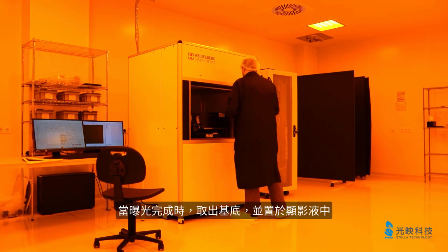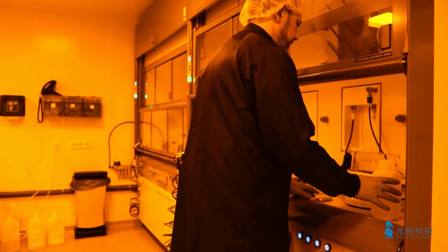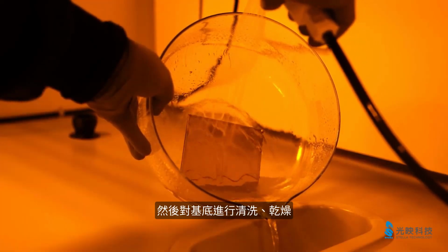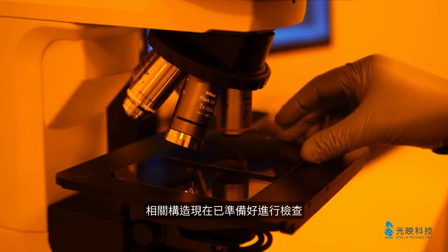When the exposure is finished, the substrate is taken out and placed in developer solution. The partially exposed photoresist is removed during the development. Then the substrate is rinsed and dried. The structures are now ready for inspection.